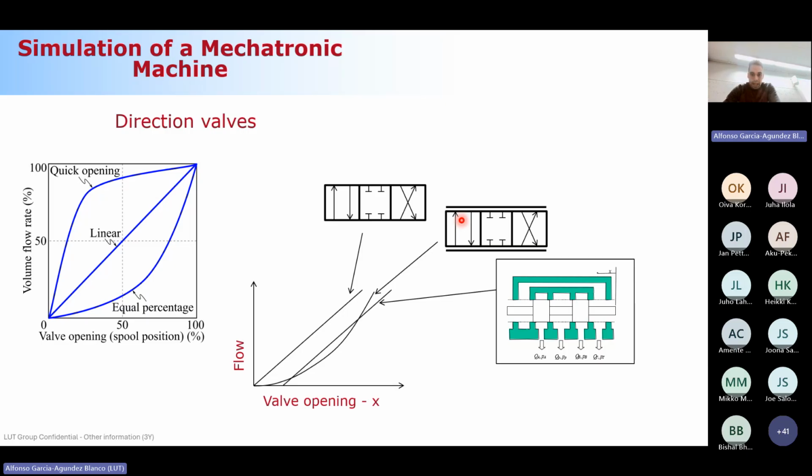And this final case, which is the one that we showed before with the thicker cylinders in the spool, would have this curve. Basically, in the beginning you would have a horizontal part, and then linear. Why do we have this first horizontal stage? Because if you move the piston a bit, you are still blocking.